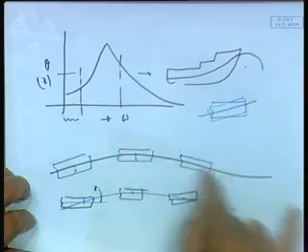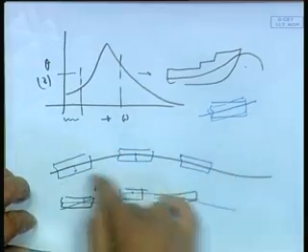Now, let us look at the phase, which is more easily seen, the relative phase between heave and pitch. Let us take an example of lower frequency. What I want to tell you is that the maximum heave and maximum pitch usually do not occur at the same time, which is good for us, because if they did occur at the same time for a given motion, you would have got a very large motion. Now, how do I see that?